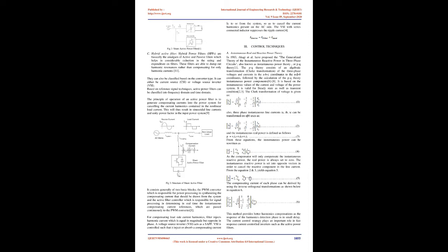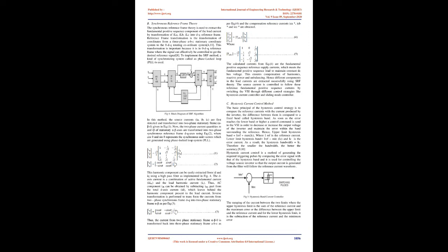C, hybrid active filter. Hybrid power filters, HPFs, are basically the amalgam of active and passive filters which helps in considerable reduction in the rating and expenditure on filters. These filters are able to damp out harmonic resonances rather than compensating for only harmonic currents.